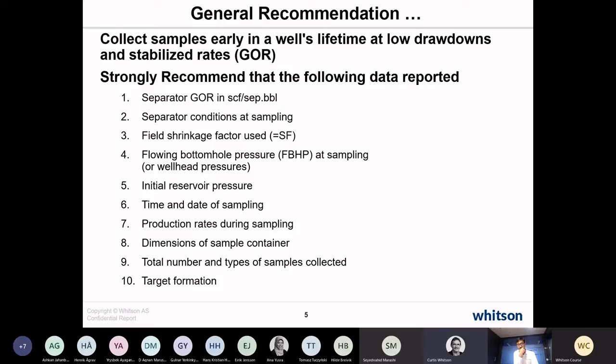So this zi, the composition variation, can come for various reasons. If it's a simple oil, like Bilal said, low GOR oil, water flooding, simple depletion, whatever, then the range of composition is very small, and you might get away with one or two PVT samples.